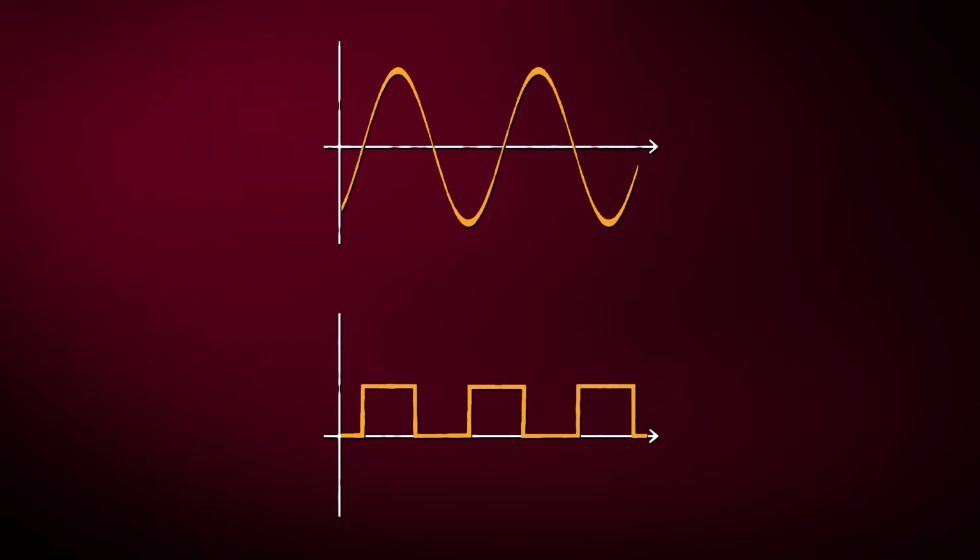These voltages are always changing in an AC signal. In a DC signal, it's pretty obvious that at this point in time, your voltage is here. At this point in time, your voltage is here. It's always the same voltage. In the AC signal, this wave is continuously changing. Here is a different voltage in time than here. So how do you represent that entire signal? You use what's called RMS voltage.